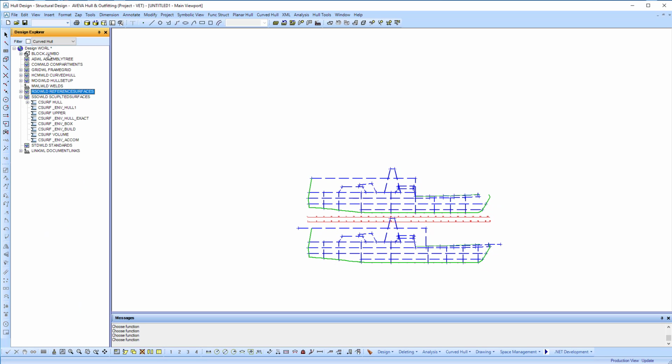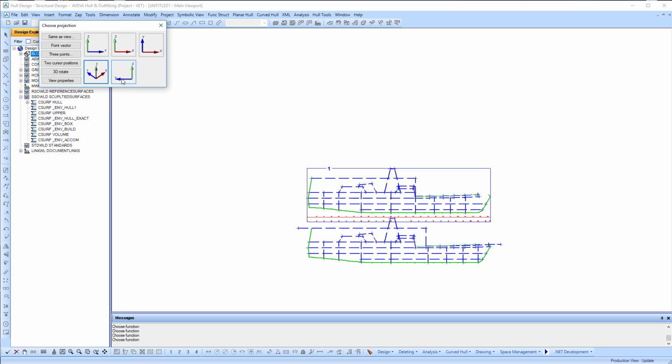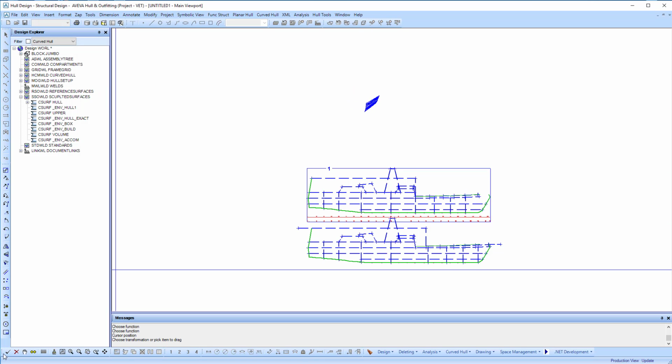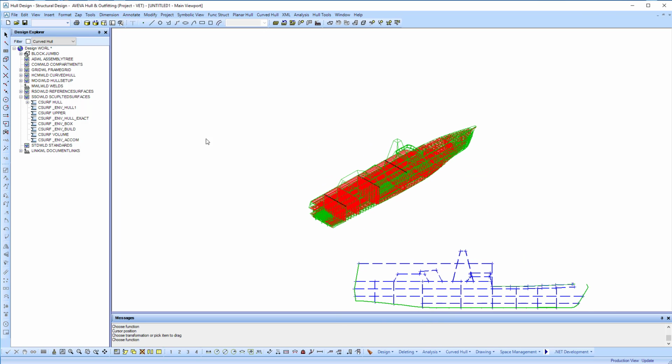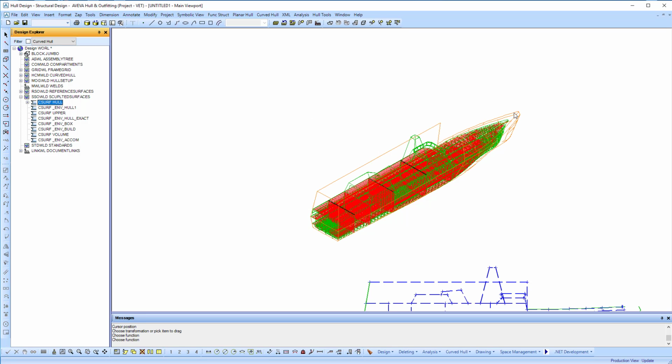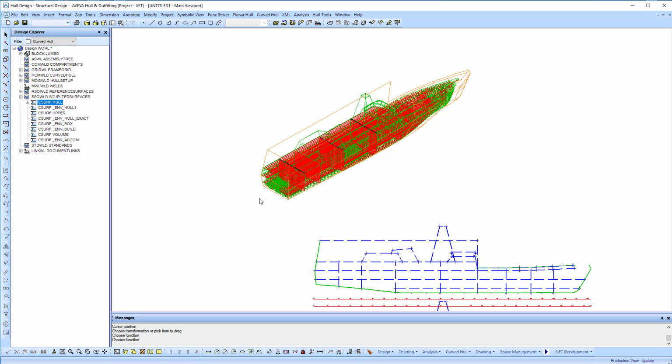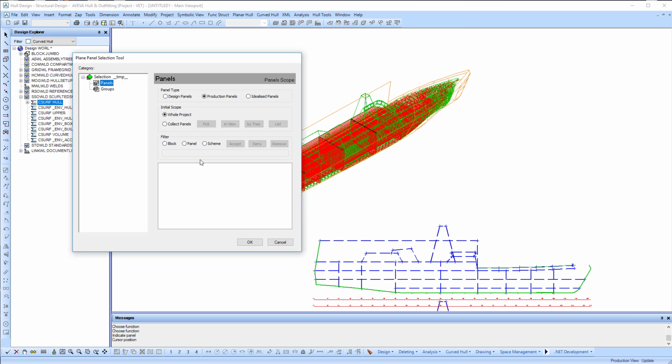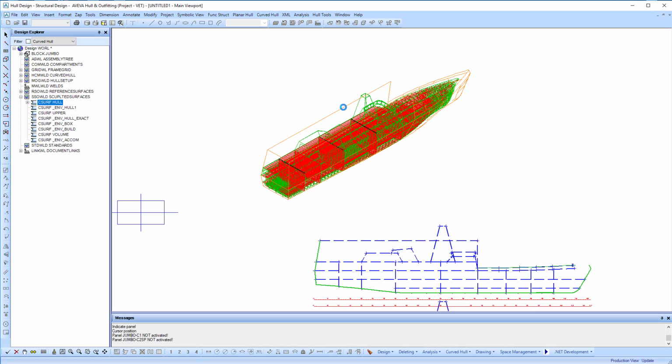So the next step is to update the planar panels. So I'll create a 3D view here, and we'll look at this process occurring. These are our existing panels, and compared with the whole surface, we've got to make that change now. We can make that change all in one go. We just have to regenerate the panels using the design rules so that they update to the frame that they've been saved on.